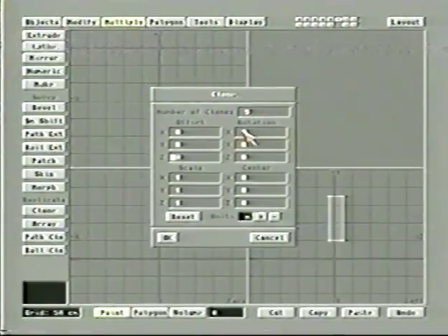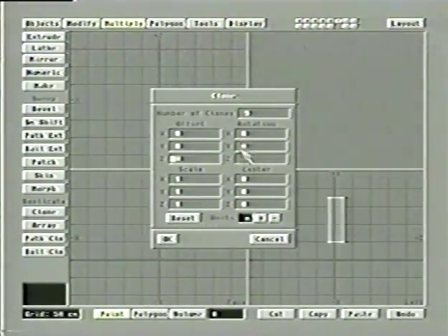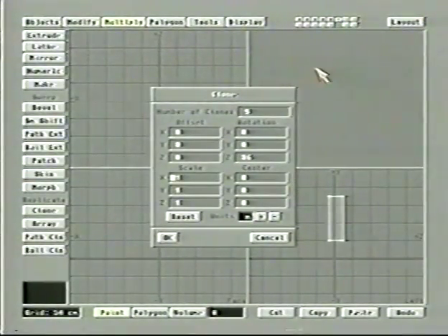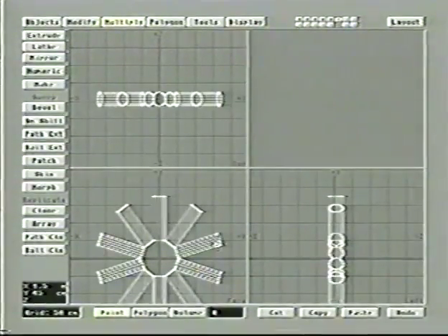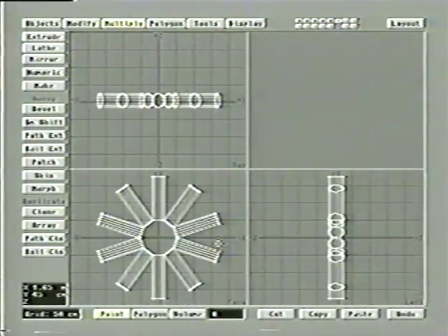So let's set it, and since we've got it set here, we want rotating around the z-axis 36 degrees. And again, the way I know that is just if I rotate it, so you pick whatever axis you need here. Since the object is facing up like this, the z-axis, this way each one's going to rotate like that. Remember, z-axis is forward and backward into the screen. 36 degrees of rotation, we hit OK, and there we go.